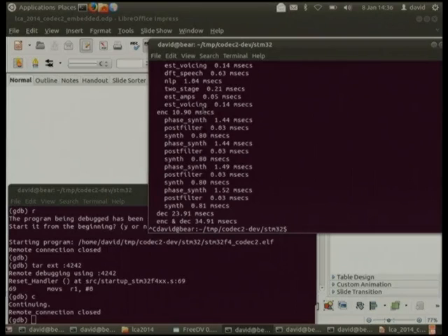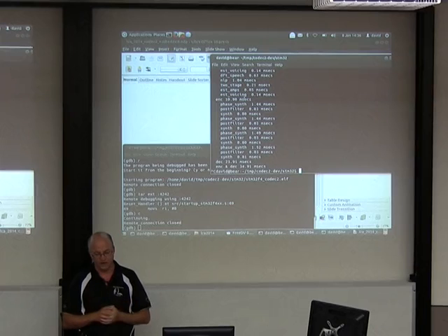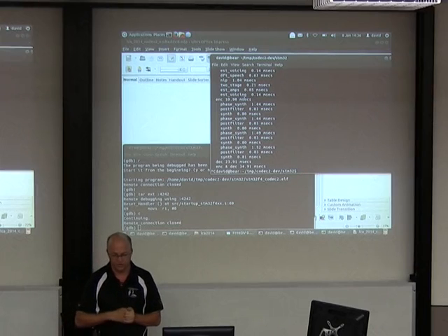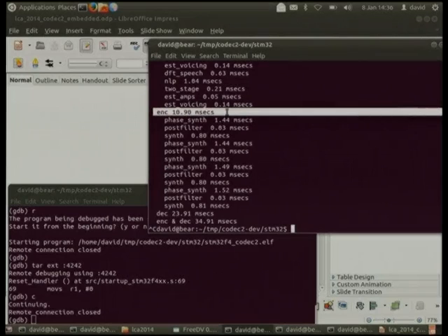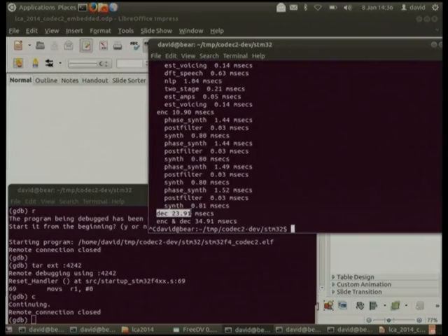I've got some code that can timestamp various algorithms as the DSP algorithms are executing. So, for example, up here, the encoder's taking 10.9 milliseconds to execute. It's got 40 milliseconds available to it, so that's taking about a quarter of the CPU of the microcontroller. And down here, the decoder's 23.9 microseconds, and this is a bunch of algorithms in the decoder. So just by printing these out, I could profile it, then go to work on the various algorithms.